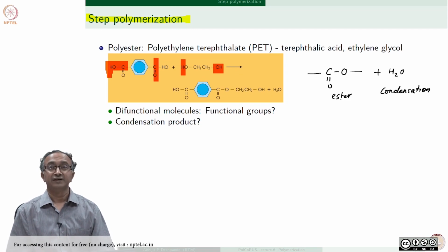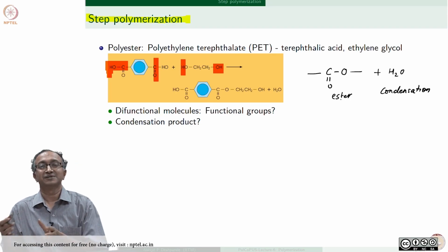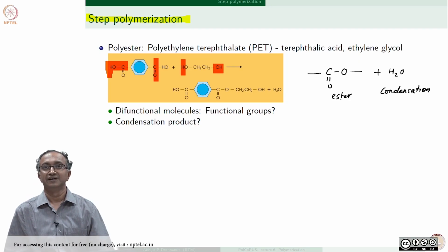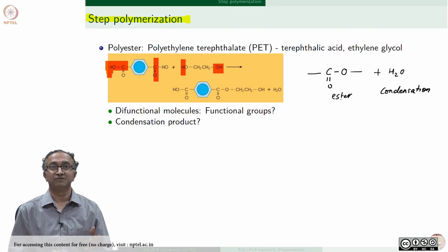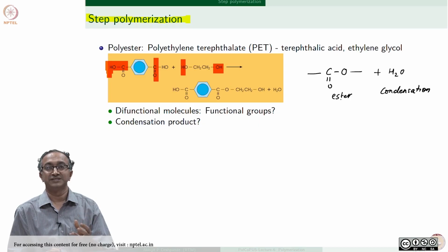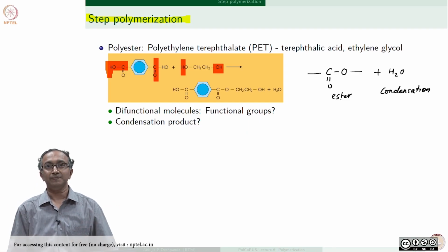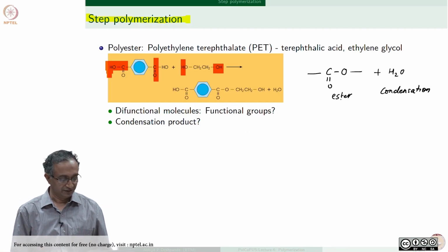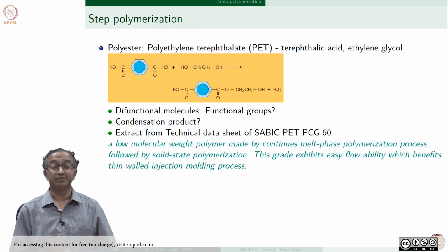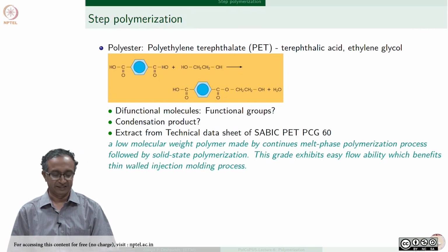In this case, right in the beginning, you cannot have a macromolecule with very long length because monomer has to react with dimer, dimer has to react with trimer, trimer has to react with trimer, and that's how in steps the molar mass increases. In case of the chain polymerization, once an active center is formed, once a catalyst or free radical is formed, immediately monomer can start attaching and then form a chain. Therefore, the distribution in each and every case depends on the polymerization method.